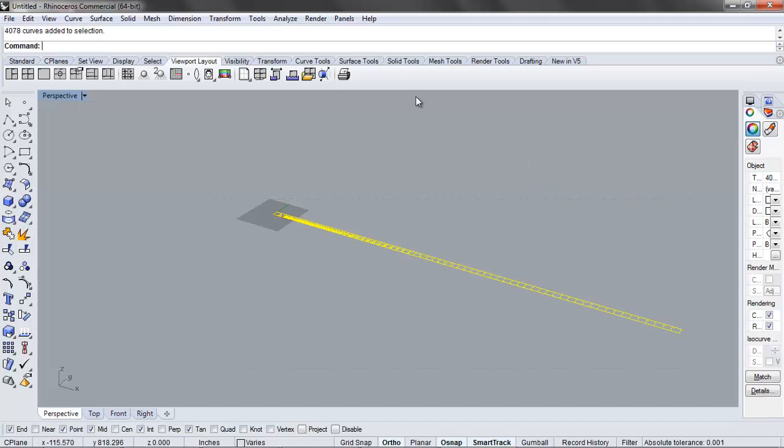Now, I'm not assigning a layer color yet because there's a glitch in Rhino 5 that it doesn't actually output ACI colors, which is what the laser cutter likes. It likes magenta, it likes red, it likes blue, it likes cyan. We'll handle that in the AutoCAD file.